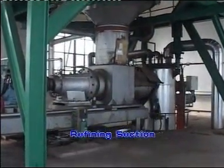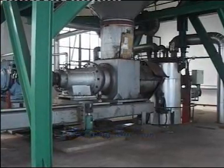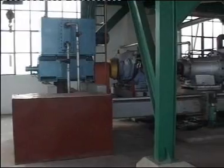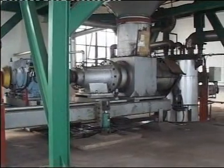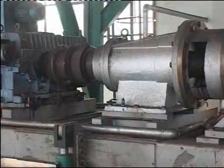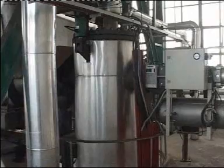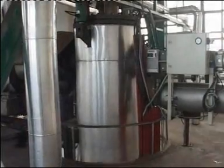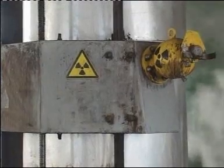After pre-steaming, the chips are fed into the plug screw feeder of refiner via vibrate device. The conical shaped feed screw compresses the chips into a plug, and the chip plugs are fed into vertical digester where the chips are softened.